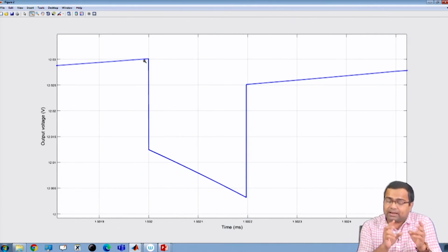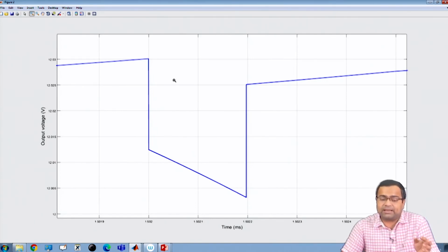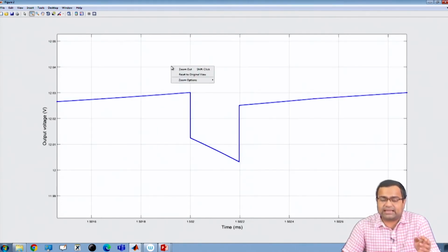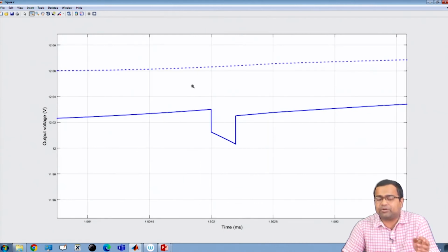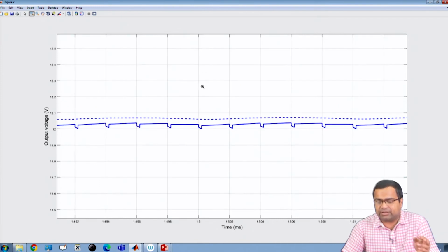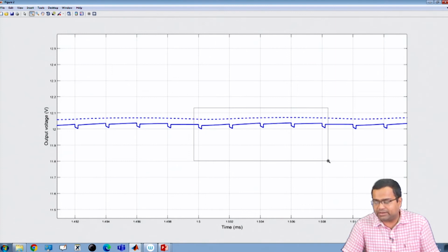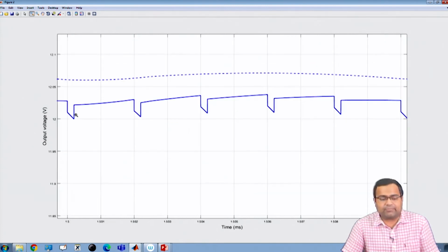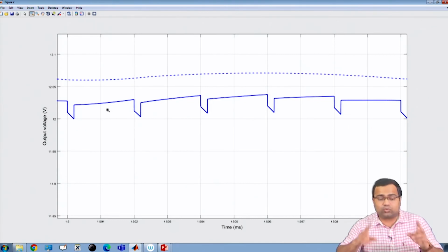That will appear at the capacitor of the IBC, which has an ESR. So, there is a discrete jump which happens in every switching transition of the POL converter, and that will happen 5 times in a cycle, and you can clearly observe that from here. If you take from here to here, there will be 1, 2, 3, 4, 5, and so 5 times. Okay.